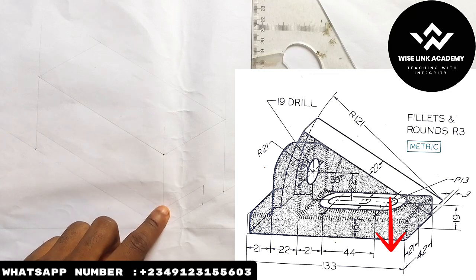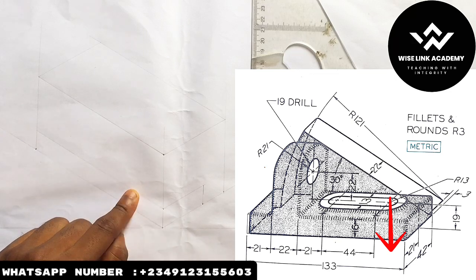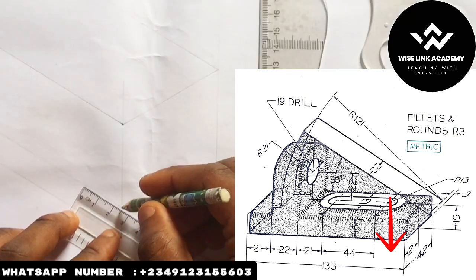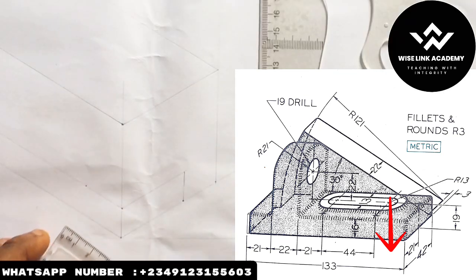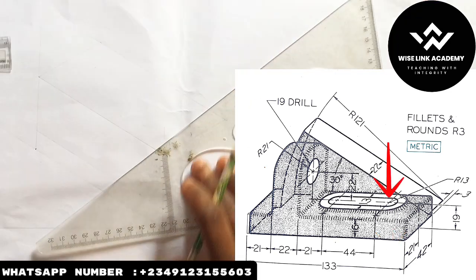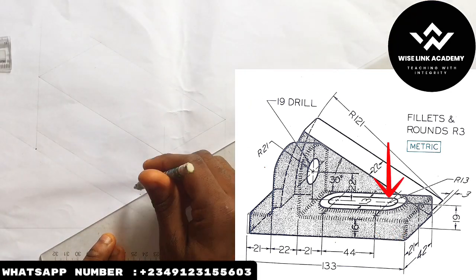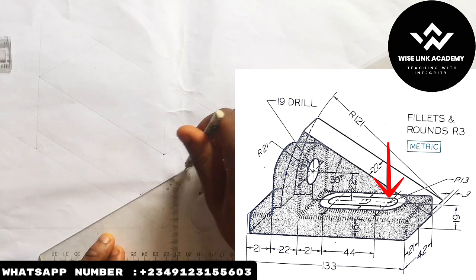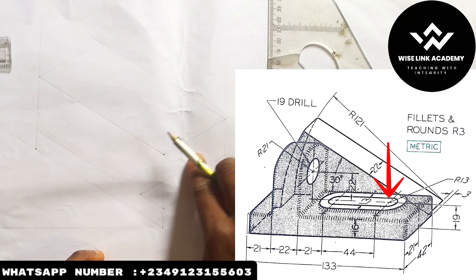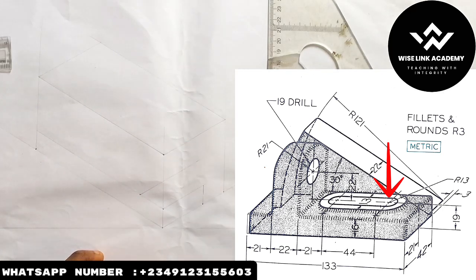So I'll move a distance of 25 because I get what that 44 you are seeing. So I'll measure 25. So from here, measure 25. From here to here is 25 to this point. At this point here, so this point here is my first center. How? I'll take this one down this way with a faint line. As you can see what I'm doing. So somewhere on this line, my center for the first one is there.